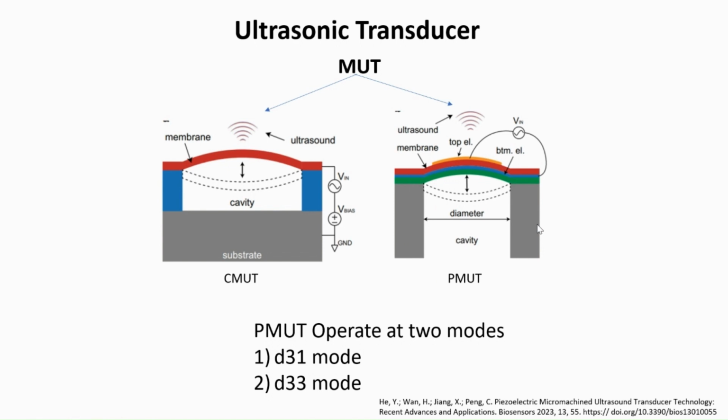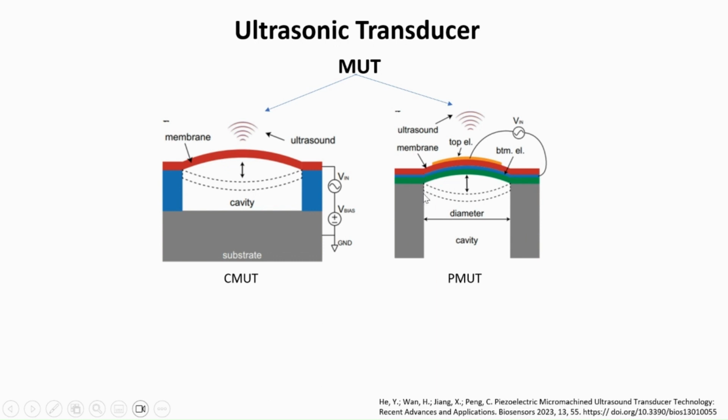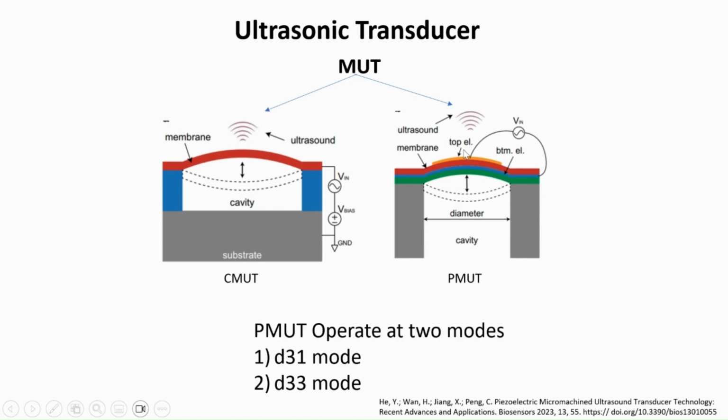When you apply an electric field in this direction, you get a strain in the x direction, and because this is clamped on both of these two sides, the expansion and compression, given an AC signal, and the strain in the x direction with this fixture on both sides, cause it to start vibrating in the z direction. That is the idea of what is happening here.